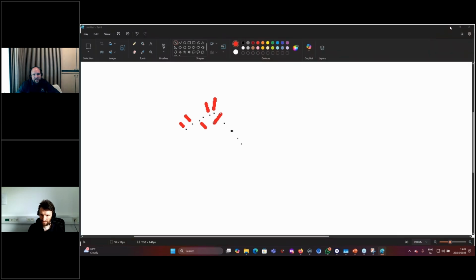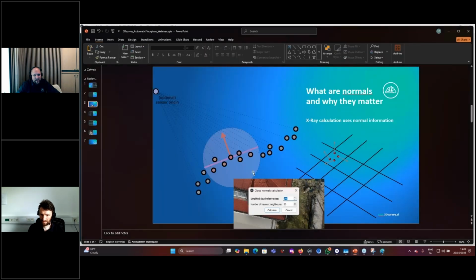If your point cloud does not yet have normals, you might not get the result you want. We are actually solving this by changing how mesh calculation works, and our plan is to have that solved with the next update. So if possible, make sure to export from your LiDAR processing software a point cloud with normals.